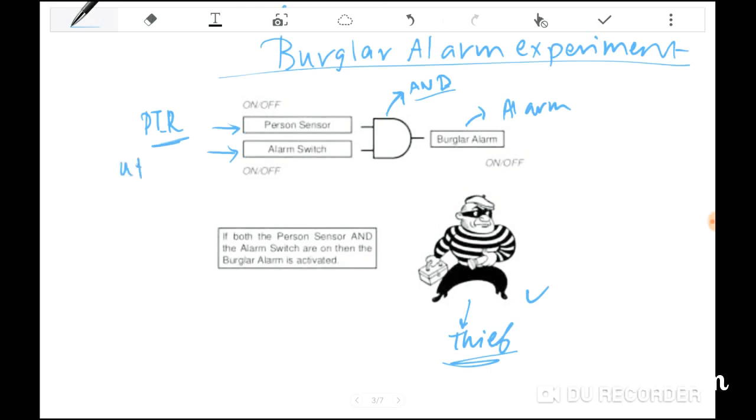an ultrasonic sensor. That is my favorite sensor, the ultrasonic sensor. Ultrasonic sensors are those sensors that have frequencies between 15 kilohertz and 75 kilohertz, and these are active detectors that transmit ultrasound waves. Whenever the surfaces are stationary, in the sense that whatever object is in front of the sensor is not moving at all, it is still, that is called stationary. The frequency of these waves detected by the receiver will be equal to the transmitted frequency.